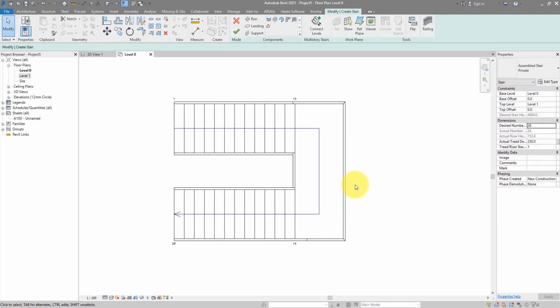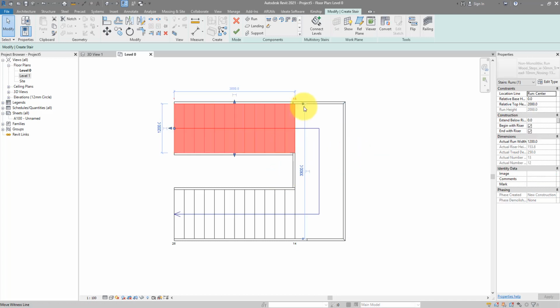Because we're using stair components, you can see the landing has been automatically generated. I can then move this one closer to the other one. Just change this dimension here. We should try to set it to measure the gap between those two stair flights. I can do so easily by just adjusting these blue points. And now I can change that to 200.